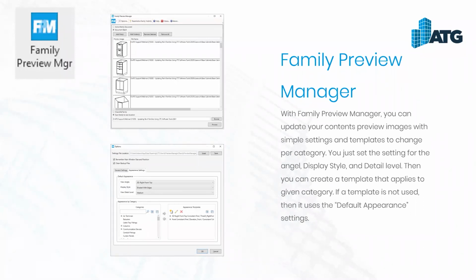So not only will it run through your families and generate the preview images, but it will also say for certain types of categories, I want you to do this particular thing, whereas on these other categories, I want you to do a different preview. So you have that ability in this tool with the options to specify templates that are applied to certain categories. Otherwise, if you don't apply a template to a category, it simply takes the default appearance settings that are set at the top.